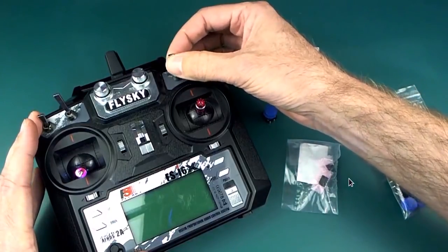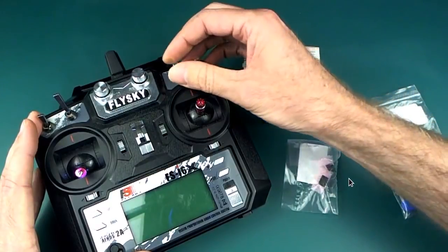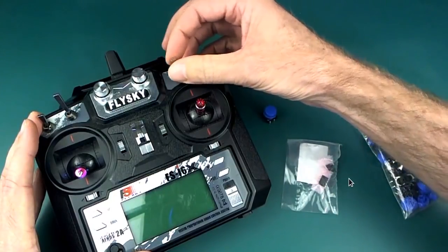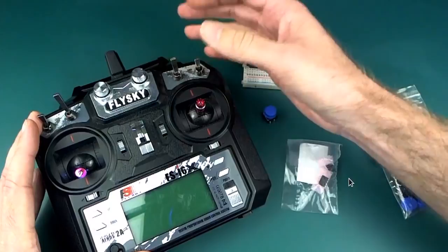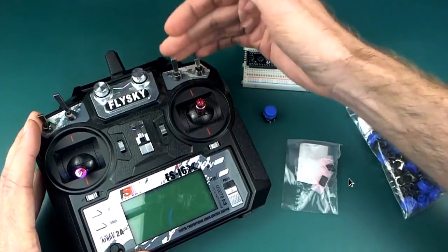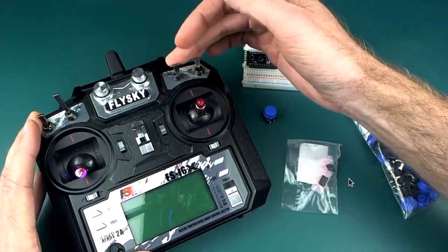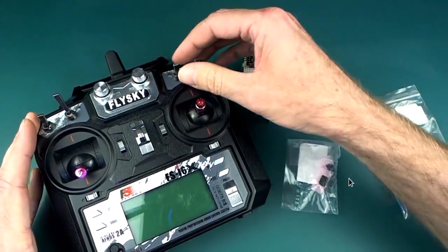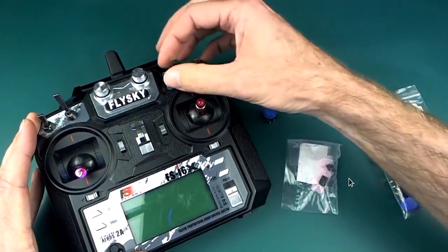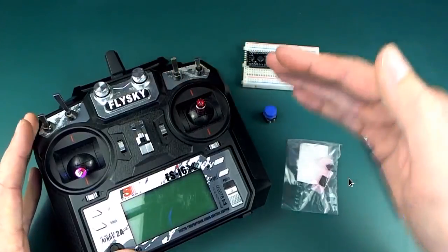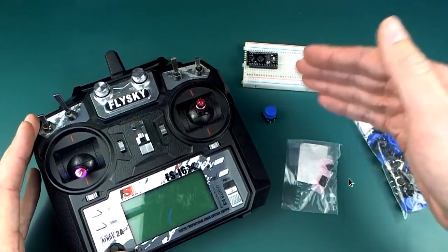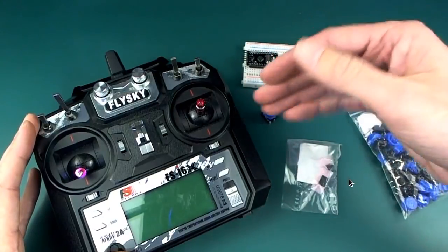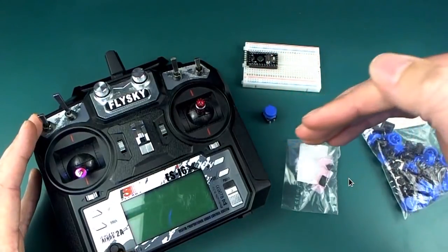So if I'm in manual and I wanted to return to home, I have to pass through the middle position, which might be auto or fly-by-wire A or whatever it is. I have to go into that mode just briefly to get through to the other side. And in some situations you might not want to do this, particularly if this was auto mode and you had a mission where there were some commands at the beginning of your mission that you didn't really want to run until you were actually ready to start the mission.